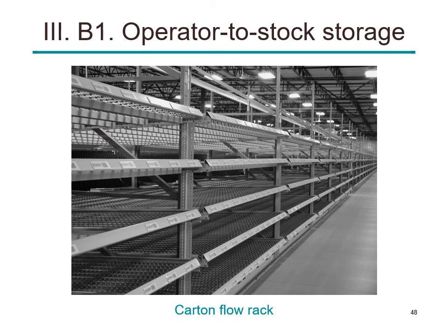Another system for small load storage is the carton flow racks. In fact, this is similar to the unit load flow racks for unit loads. Again, in a similar idea, there are rollers on these racks, and when you place an item from the back end, with the help of gravity, it slides to the front. So the cartons are placed one after another, and whenever you use one carton from the front, when it's finished or removed, all others slide to the front, and this facilitates the use of first in, first out system.